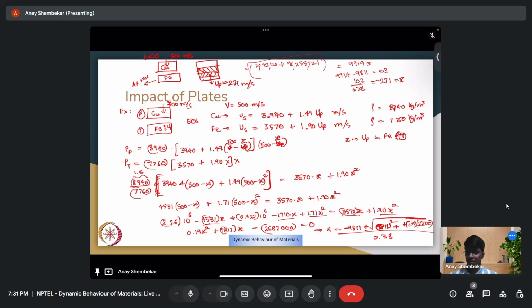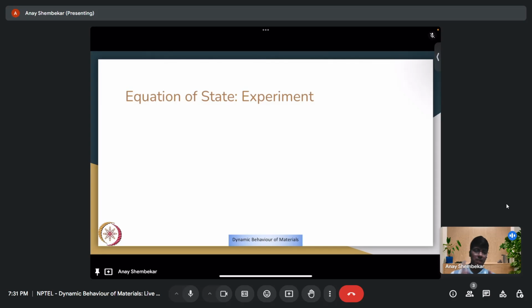Okay, but apart from solving this kind of an equation, this parallel plate impact and shock waves being generated is useful in another way to help us determine experimentally what the equation of state looks like. So, as we have already seen, you have got 5 parameters in the shock wave and 3 conservation equations, these being mass, momentum, and energy.